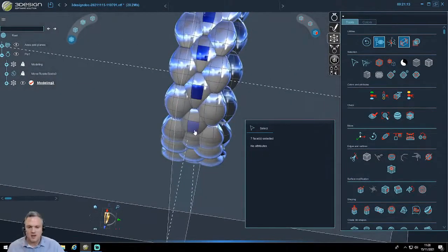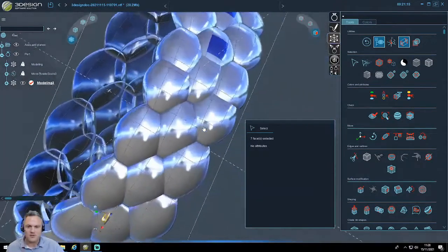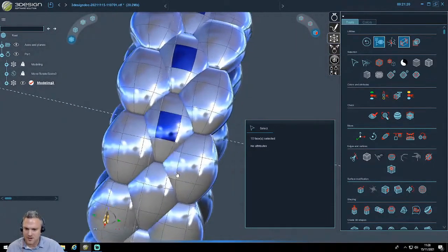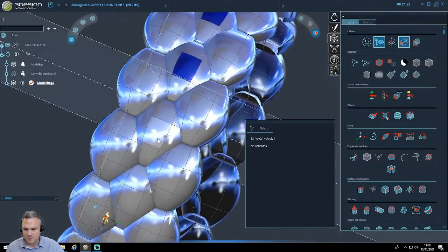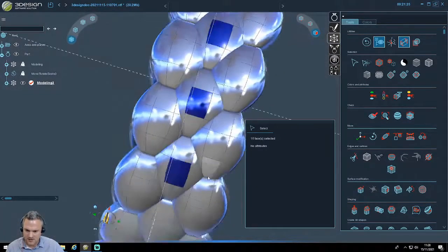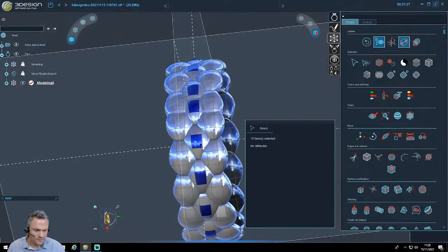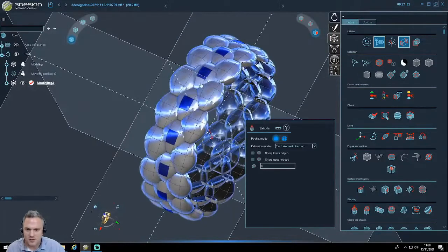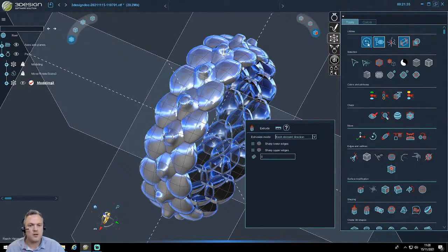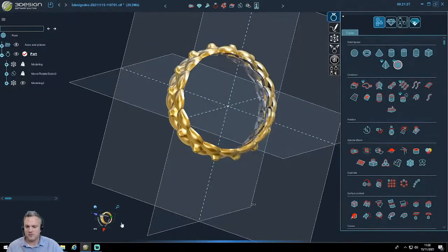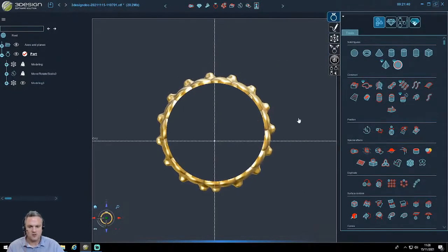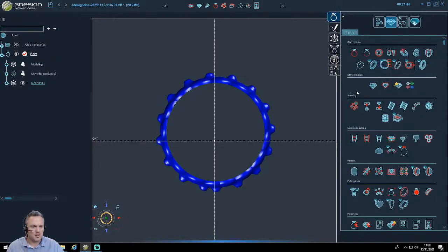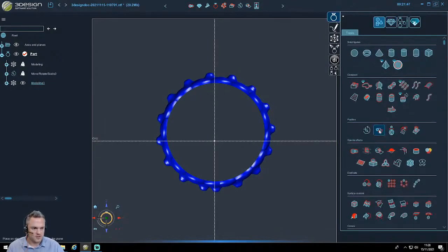You have to know also that I'm using the 3D connection mouse, which can be really useful for 3Shaper and 3Design. Then you can easily turn around the ring and select what you have to do. So for example, it can be an extrusion from that one. Up. And then after, I can use, for example, something which will be a sweep to draw the ring. Let me select that one.